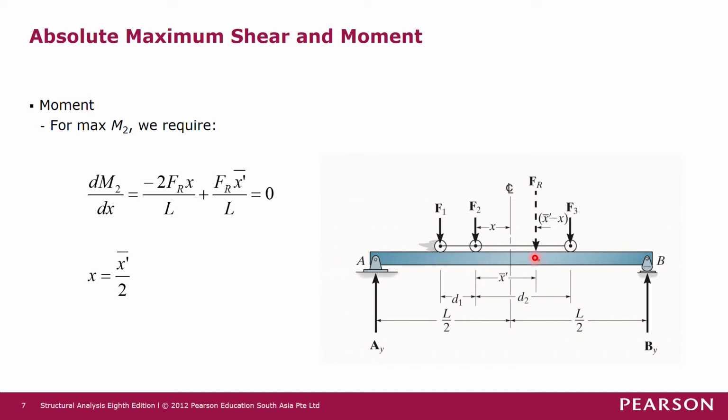And then you plot the graph and determine the location of the maximum moment due to this system of forces. So in that case, you have to do a lot of analysis, a lot of influence lines to draw. You have to draw influence lines for at least 3 or 4 points, and then determine the maximum moment due to the moving load in each case.